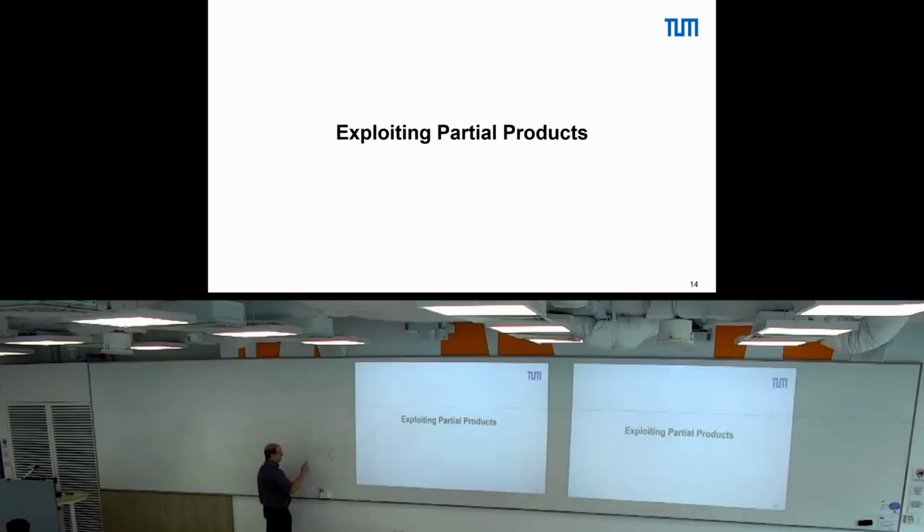For binary, if we have two numbers, let's say 101 times 101, then our first step is, let's start with the LSB. MSB doesn't really matter, or with the MSB, well, 101. We add 101, we add 000, we add 101, right? And then we add up. So a partial product is we multiply this here with this here. We multiply this here with this, we multiply this with this. Gives us these three partial products.